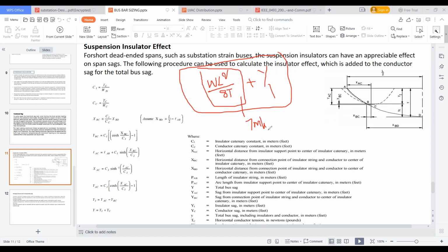Generally, 7 meters will not occur for your project, maybe your project is located in a normal range of temperatures and ice loading. If you calculate the actual sag using sag templates, considering the worst temperature in your region and the worst expansion of your conductor length, and you find 4 meters, then there is a 3 meter delta. So you can do the optimization on the tower height or the clearances or the tension, whatever it may be.